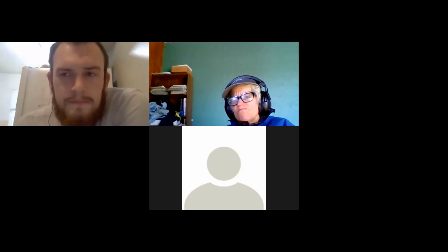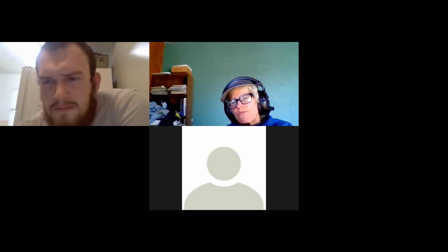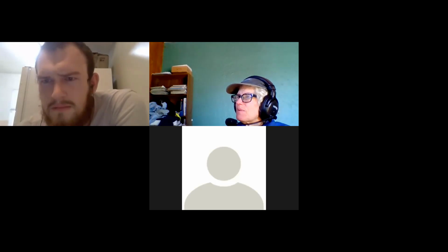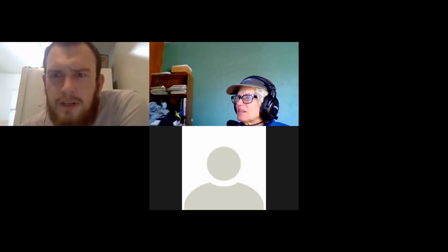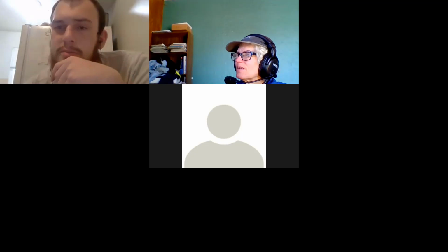Do you mind if I interject? What if somebody just pulled Q5 and Q6 out and asked you about them, what would you say? It looks like it's a Darlington pair, maybe. Yeah. Oh, so maybe Q5 and Q6 are some sort of biasing for Q7 and Q13.